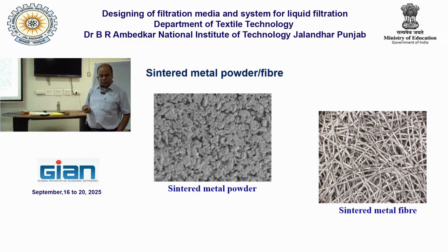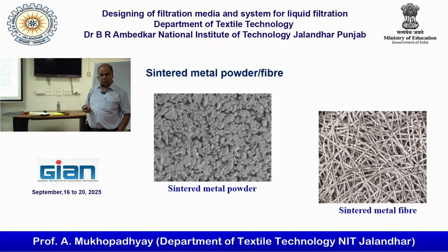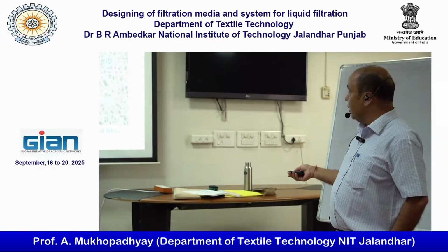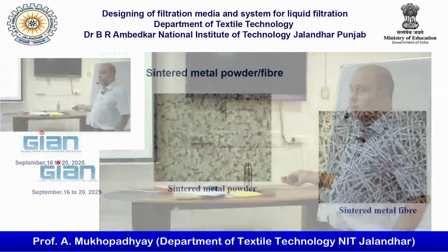Whether the fiber form will be in hollow form? No, the fiber will come out in a polymer form, but it will be a kind of porous type of structure. It will take up some form of the fiber because of the sintered metal. But the advantage over this is that it will give you better capability for the fluid flow. In powder form the fluid flow resistance will be more. In fiber form the fluid flow resistance will be less.